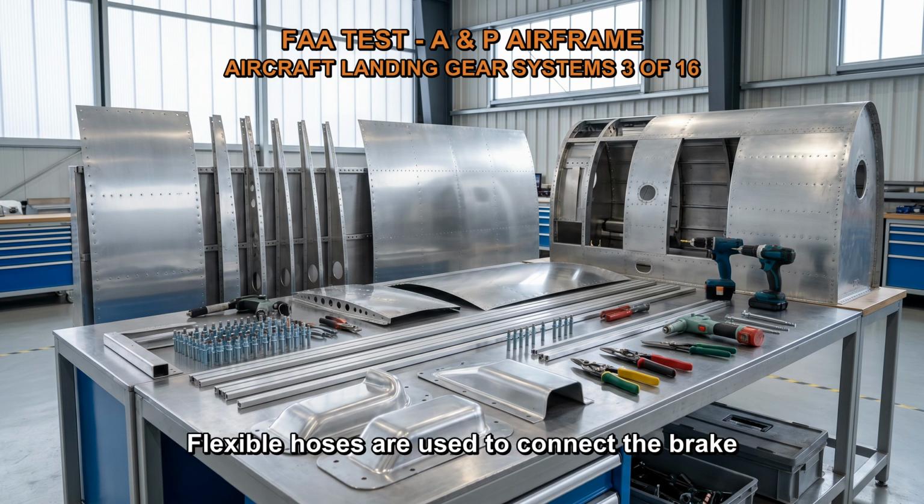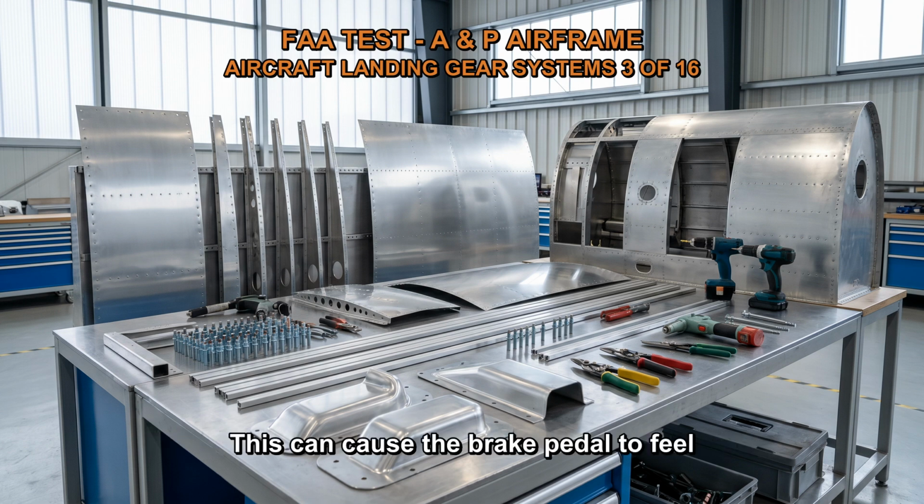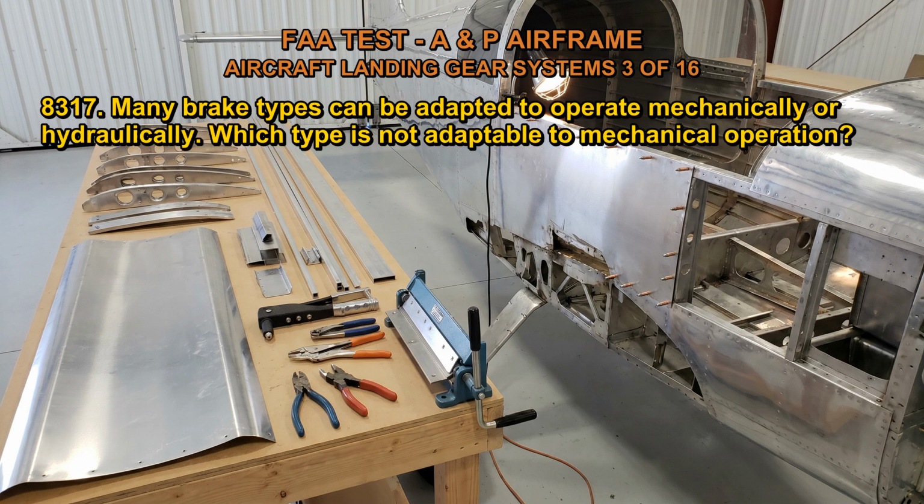Flexible hoses are used to connect the brake lines to the brake calipers or wheel cylinders. Over time, these hoses can deteriorate and develop leaks. This can cause the brake pedal to feel soft and spongy.